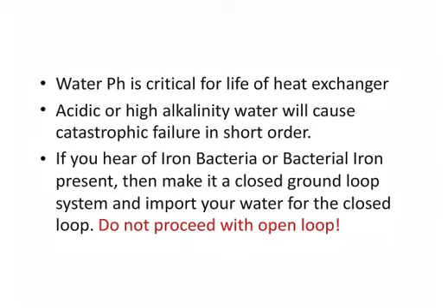Water pH is critical for the life of the heat exchanger. Acidic or high alkalinity water will cause catastrophic failure in short order. Again, it depends on just how acidic or how high the levels of alkalinity are. If you hear the phrase iron bacteria, and oftentimes it's referred to as bacterial iron, well, that is not a candidate.